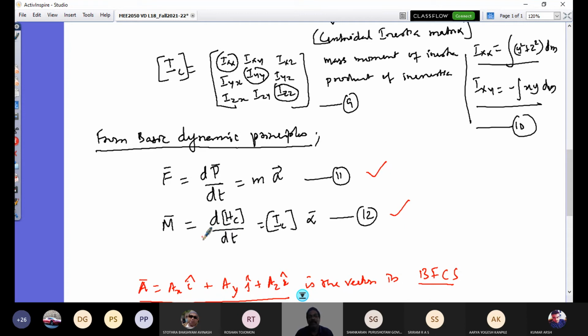And that is what is Mx, My, Mz. How do you get that? That would be analogous to the way you get your force, the rate of change of angular momentum. So that is called an Euler equation. So the second equation is what is called the Euler equation. That's why these two together are called the Newton-Euler equations for rigid body motion. And this is defined as the rate of change of angular momentum. Is it clear to you?